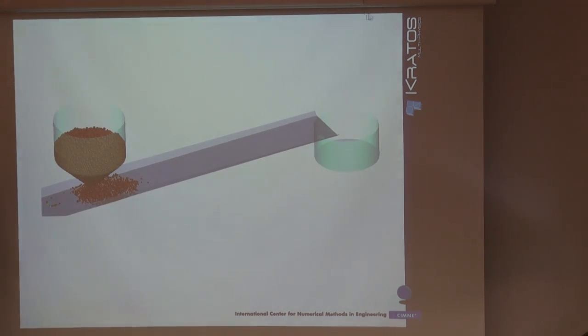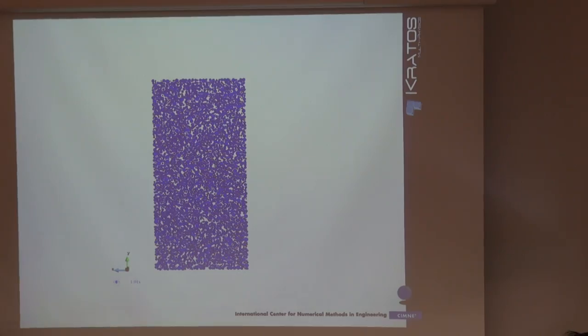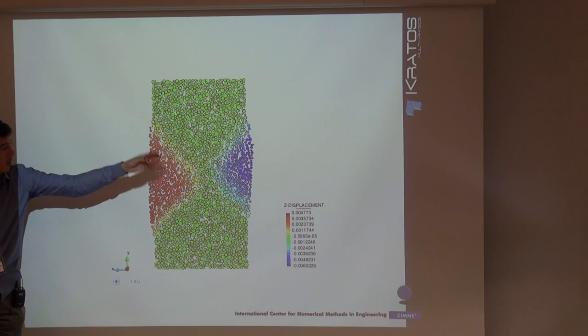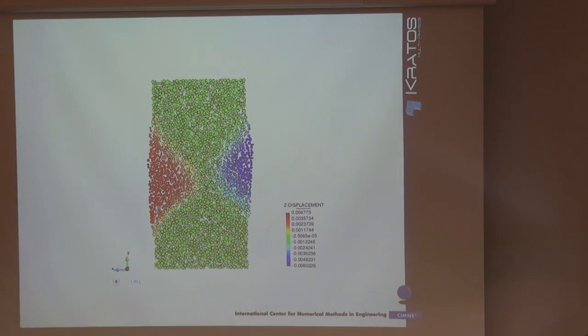This is another example where there are only particles as a matter of interest. But this is also just particles, and in this case, what we are calculating is not granular material, but this is supposed to reproduce a continuum model. And here, okay, this is a uniaxial compression test. So you can see the typical failure of a concrete specimen.